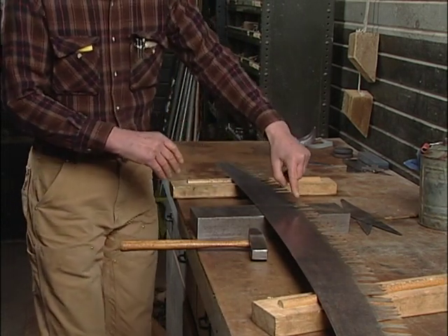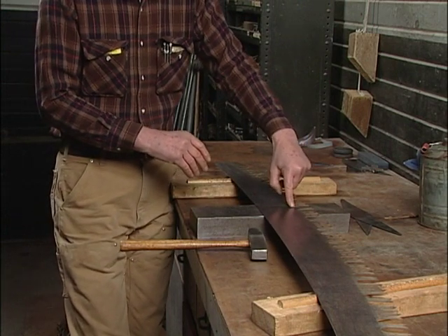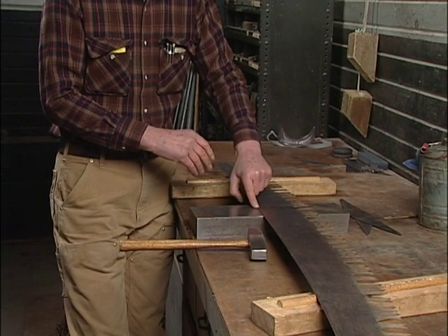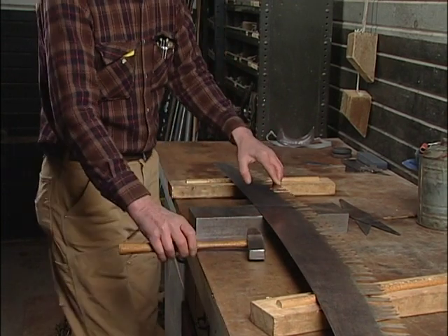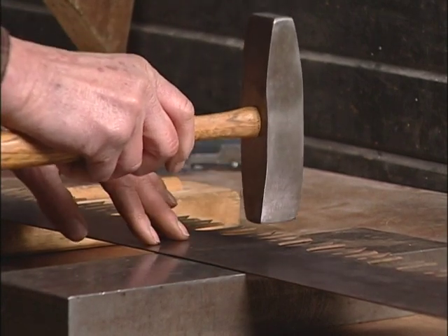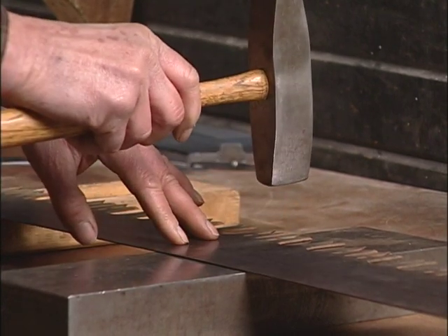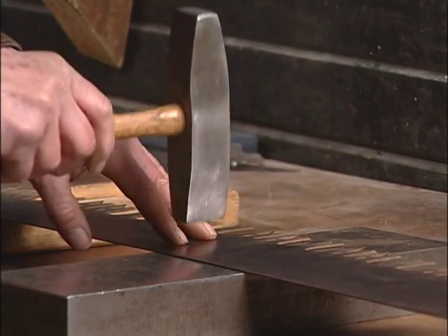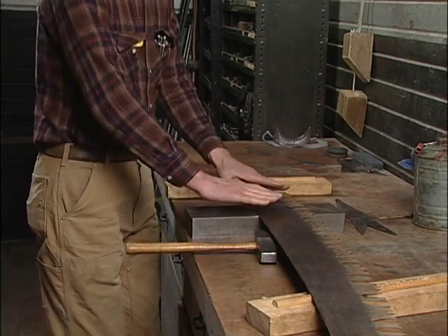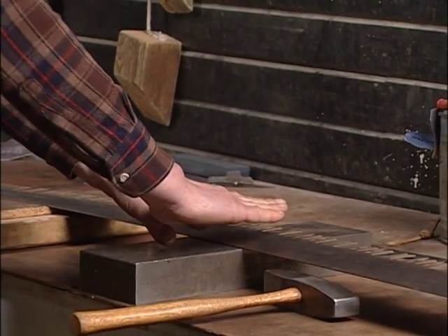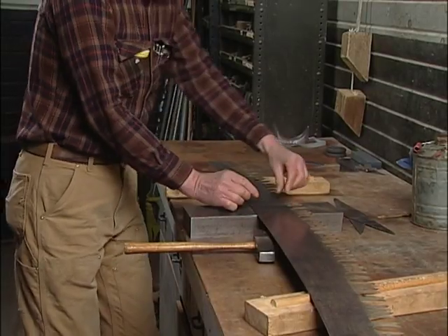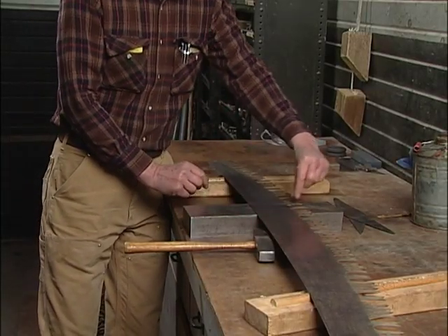And I usually start from the toothed edge of the saw, or where the gullets are, and move towards the back of the saw. Depending on how much of a kink I want to take out, I may use just 3 strikes, like 1, 2, 3, or I may use 4 strikes, like that, to get more hammer action in there. Now, with a saw that has a fairly sharp kink in it like that, that's quite easily demarked, you're only working in a very narrow area of the saw.